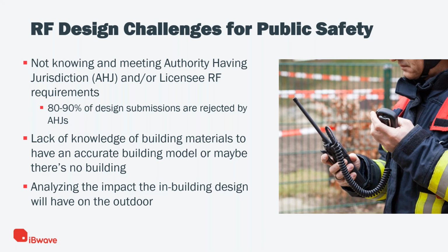What is it that you're going to be amplifying in your system? Very important to know that, right? The second challenge that we usually hear about is not knowing building materials. Nowadays, for example, if we're turning on a new building, it's very common for that glass, it's energy efficient, but it also blocks the RF. Not only that, but knowing how concrete and all these different materials inside of your building might affect the RF is also very important. And what do you do in the cases where there is no building? If you can't go out there and take measurements, it's also important to take into account the material that's going to be inside the building.